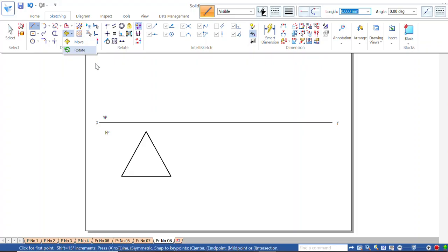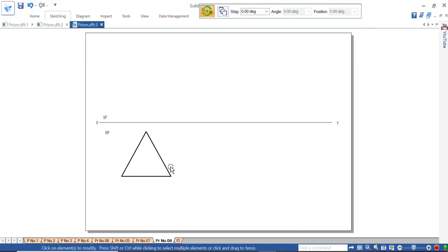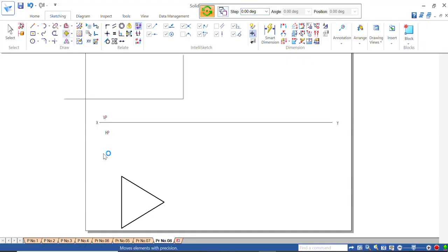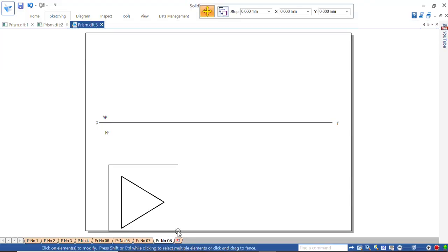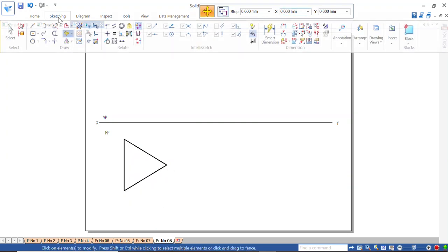You can go to rotate through window, select the triangle, the 0 degree line, center of rotation, point to rotate, clockwise 90 degrees. The angle is 90, the position angle is 270. You will get the corner, and move it wherever it is nearer to the XY line.